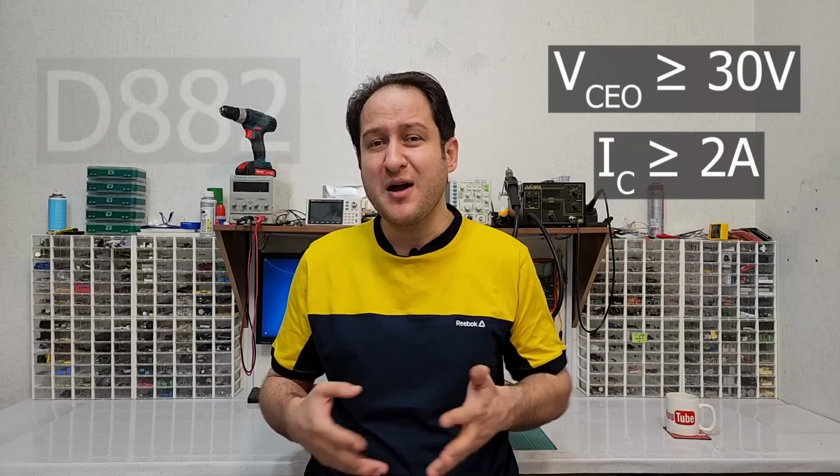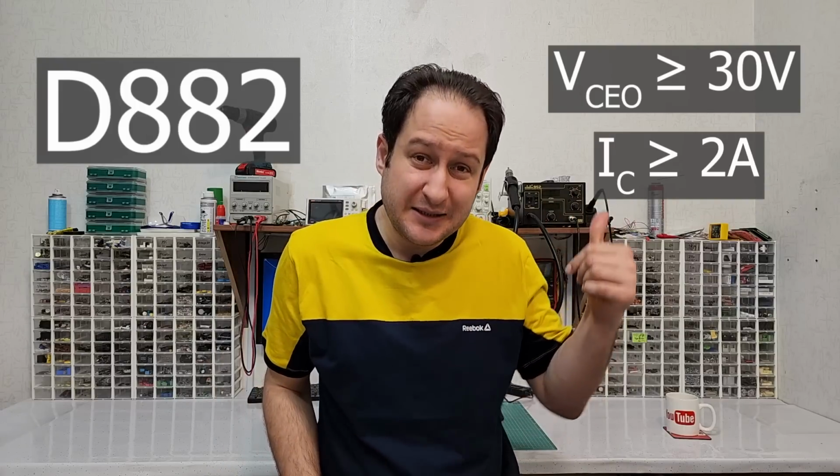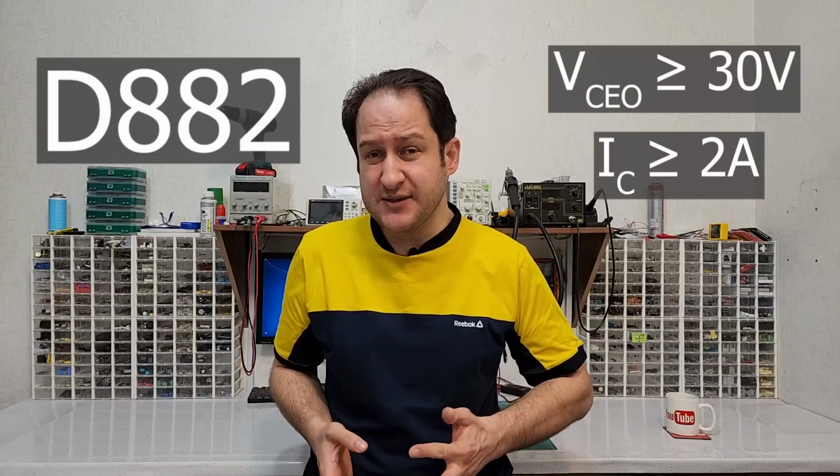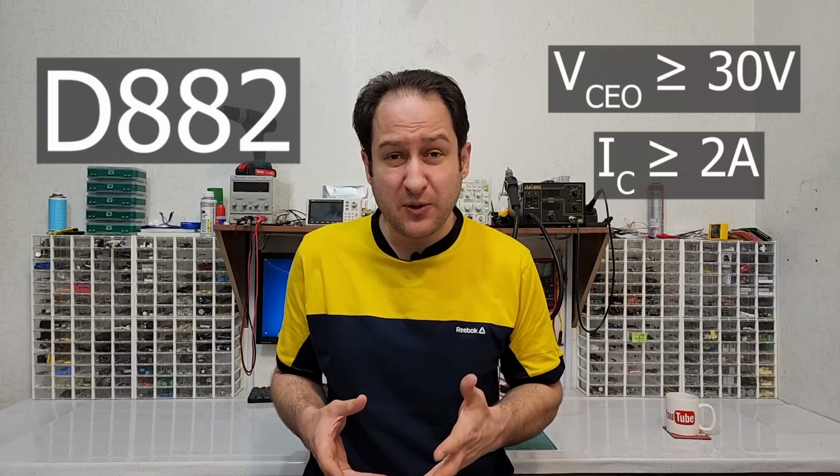While I was looking for the right transistor, I came across D882, and guess what? It perfectly met these conditions. I mean, it's an NPN transistor, the VCEO is 30 volts. However, it would be better to choose a transistor with VCEO higher than 30 volts, not exactly equal to 30 volts, to have a safety margin, and the collector current is 3 amperes. It seems that this transistor fits our needs and it's a suitable choice to drive the motor. To be sure, it's better to check more parameters.